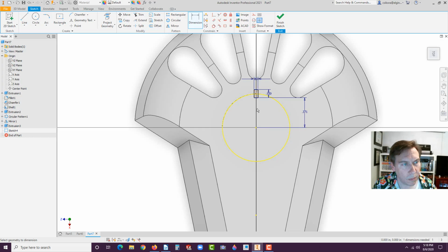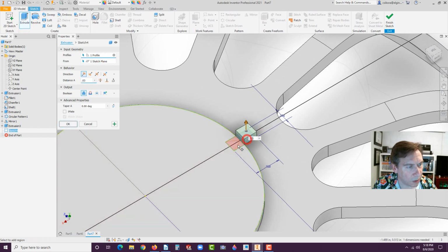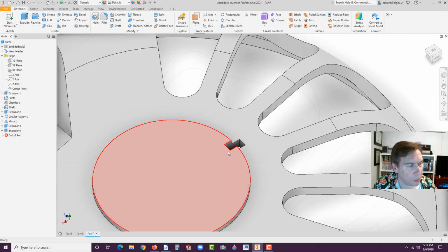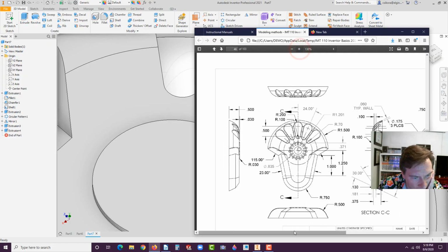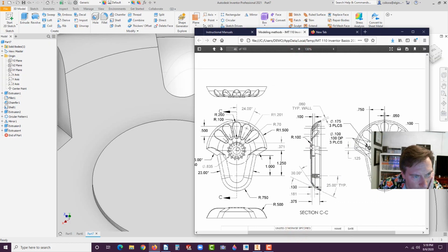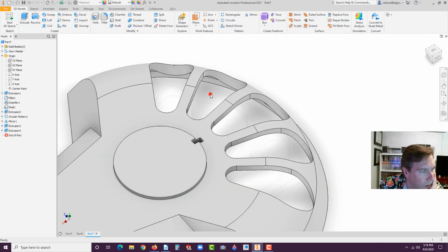And then it's located. Now we could hit 3D Model, Extrude, zoom up and select those two profiles, flip the direction through all, and hit OK. Now let's put some fillets on here. Now the radius is called out on here. You have to probably zoom up to see it. Let's see here. On a side view, there's 100 thousandths on the inside. And then there's I believe a 30 thousandths radius, yep, around the outside of that. So let's go ahead and put those in.